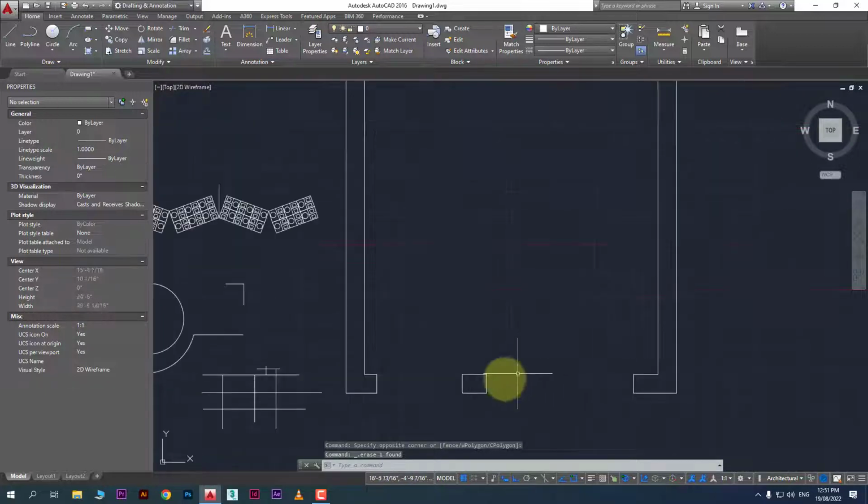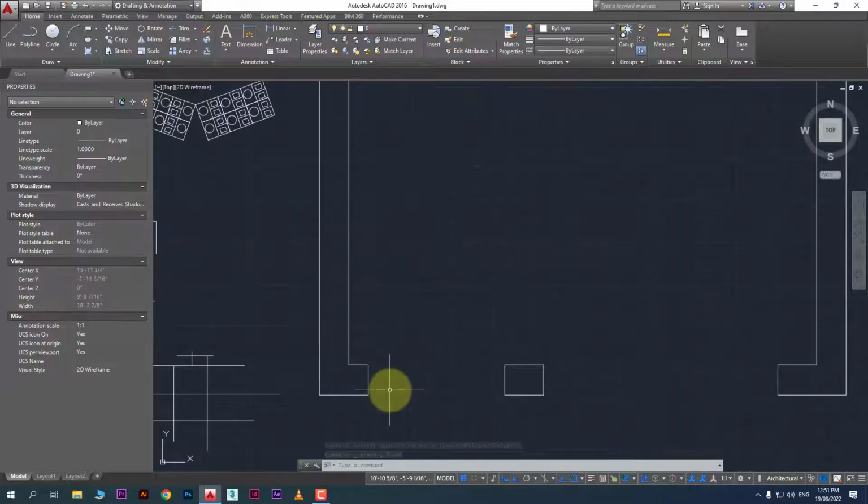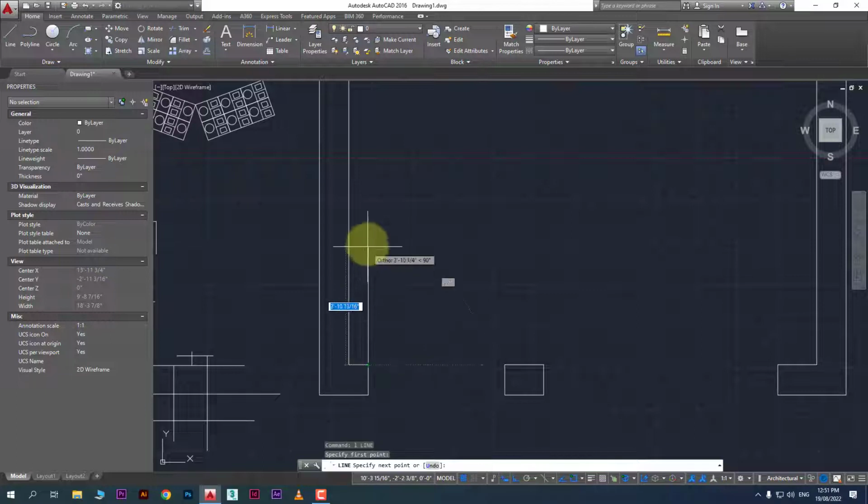If you want to create a shape for the door, take the line command from here and specify the width of the door. So make sure the width of the door, like here 3.5 feet and here should also be 3.5 feet, and just enter, because we want to close the door, so it should be equal.